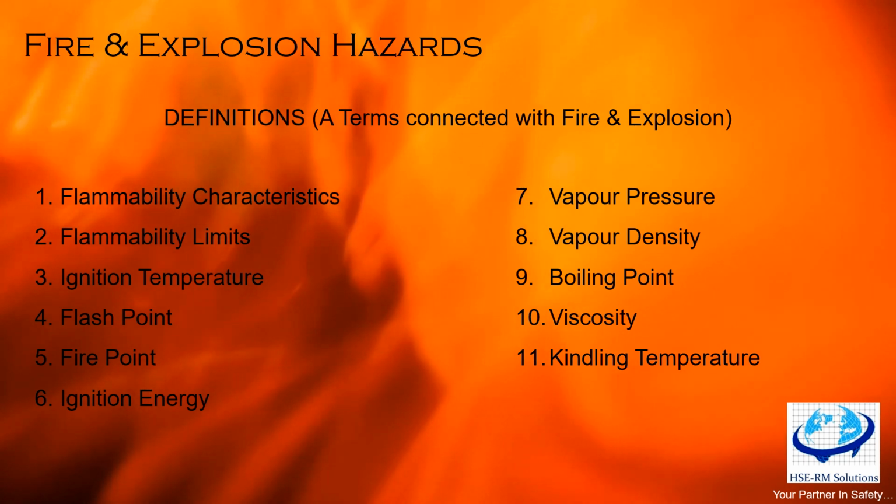So a decrease in pressure below atmospheric can narrow the flammable range by raising the LEL and reducing the UFL, that is the upper flammable limit, until the two limits collide and the mixture becomes non-flammable. Conversely, an increase in pressure above atmospheric can widen the flammable range.